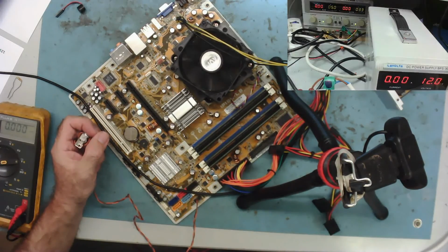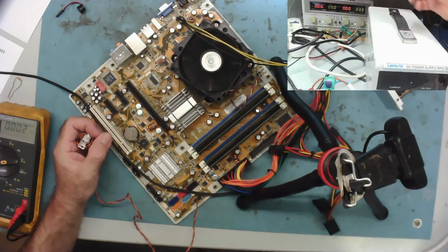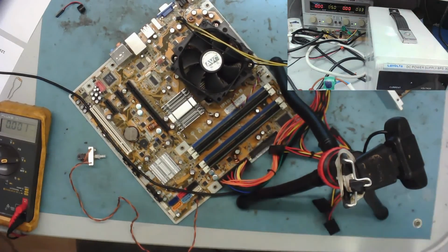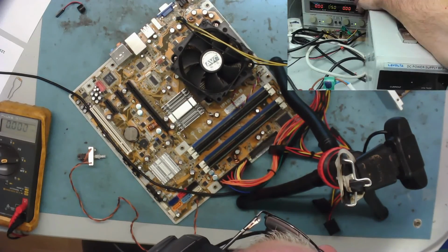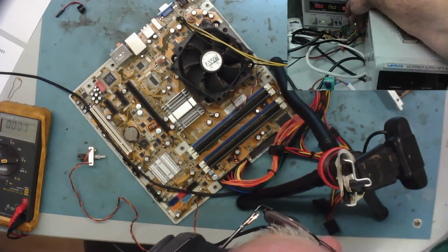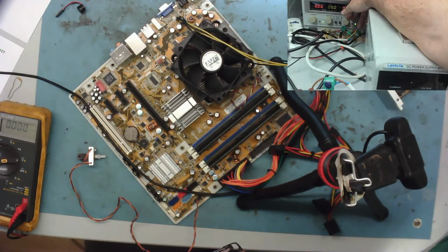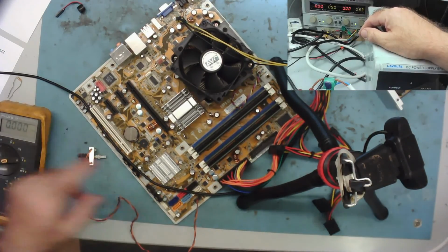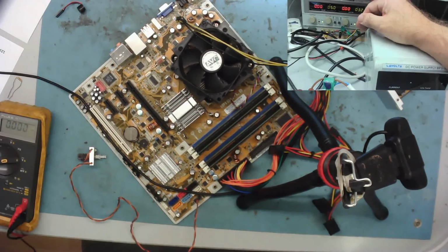What's happening is, and I just saw it, no point going any further. What's happening is this can't handle it. So the 3.3 is drawing more than 3 amps basically. I can see the constant current indicator is flashing, to say that it's dropping the voltage and it's clicking. This is why this started and stopped.